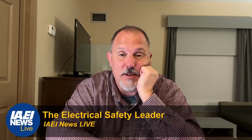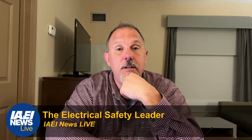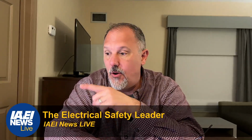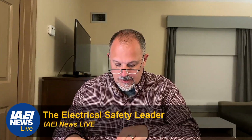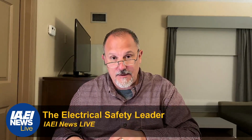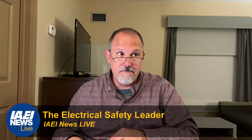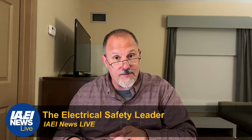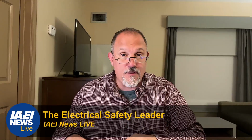To meet this requirement in the code, I would have to pull a branch circuit from the other building over to that panel board and power the receptacle separately. That would permit me to do what that requirement states in 210.63(B)(2). It's challenging. I don't know the right answer. All I do know is to meet it, that's what you would have to do. So think about that one. If you have better ideas on how to solve that puzzle, I look forward to your public input.